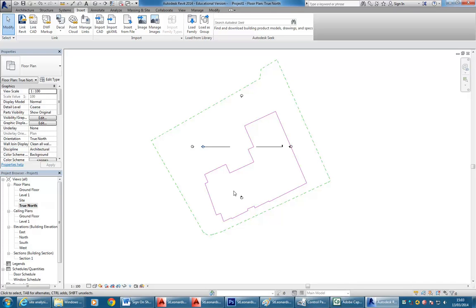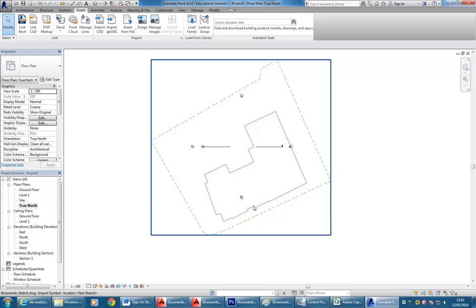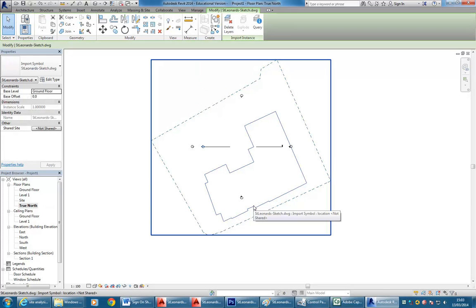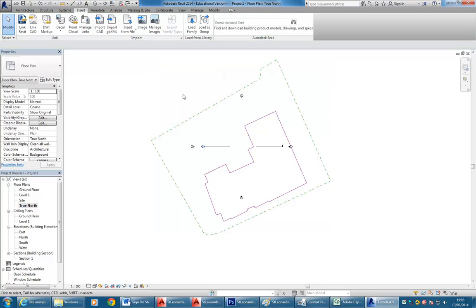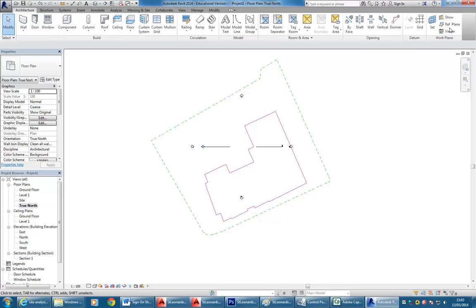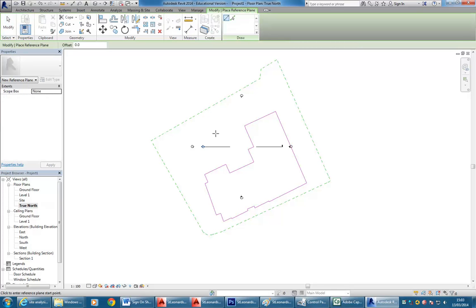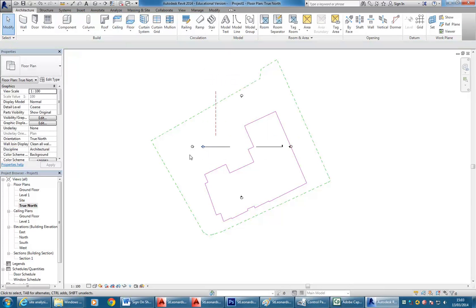Okay, so do you remember then what the next thing, what we're trying to do next? If I've got the drawing inserted like this, well, firstly, I'll just maybe ask you, True North. How do I know True North? It's straight up, exactly. It's come from Google Maps, right? Google Images or Google Maps, and satellite view. So that means it's just like most maps with north straight up the page, and I can indicate that for myself with a reference plane.